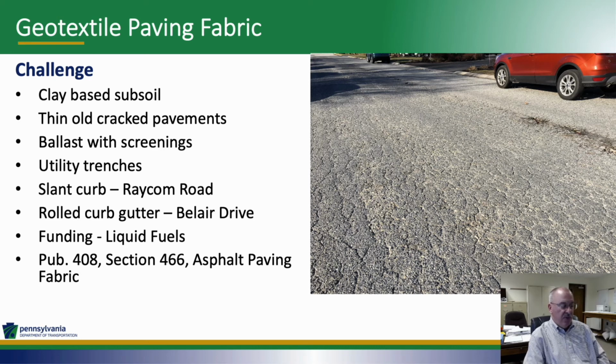And you'll see in a photograph the existing alligator or chicken wire cracks. This was on Bel Air Drive. Although the road was severely cracked, it has more than 8 inches of ballast with screenings as a base. We had no areas of mud pumping up through, and that allowed us to use the fabric and not have to do a lot of base repair. And keep in mind, these two roads that we did were over 25 years old.